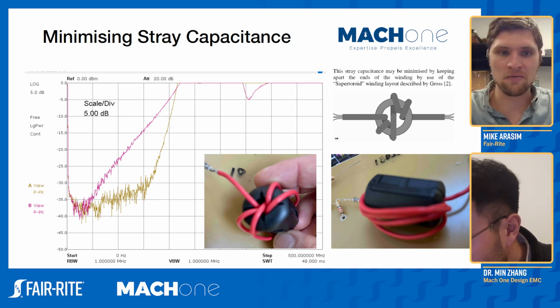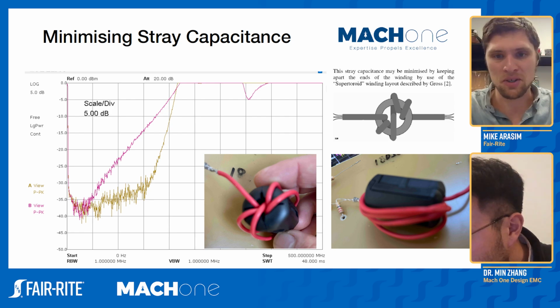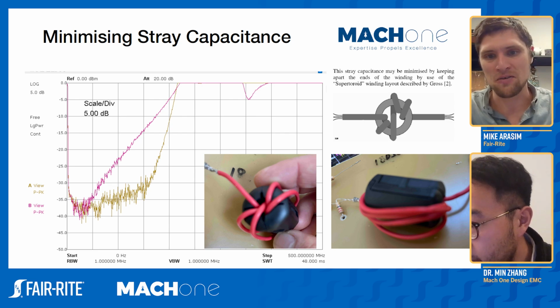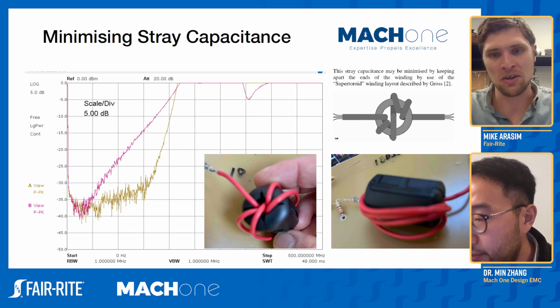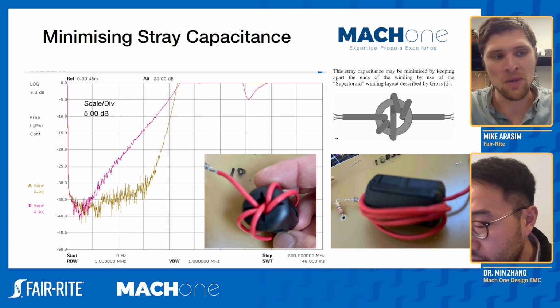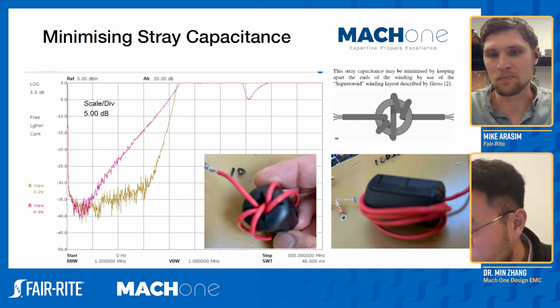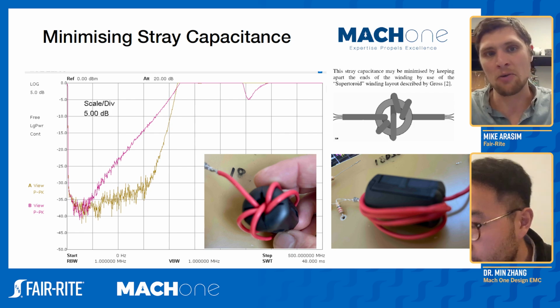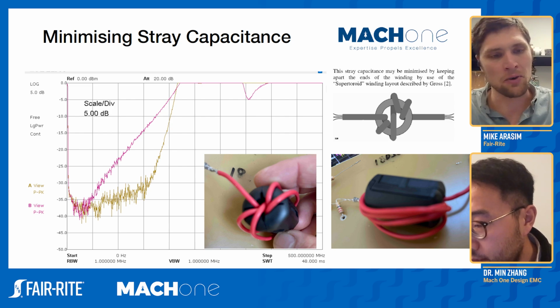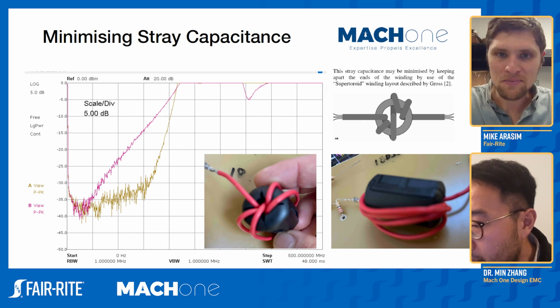So you're going to have, at some really, really specific frequency, massive, massive impedance that you're registering on an impedance analyzer. But you'll notice that impedance curve is going to just drop like a rock right after that frequency. So you may wind up going backwards at the higher frequencies from having too high of a turn count on the core.